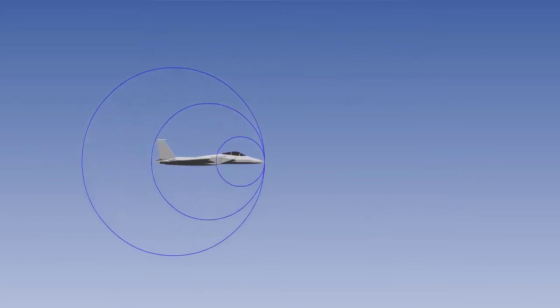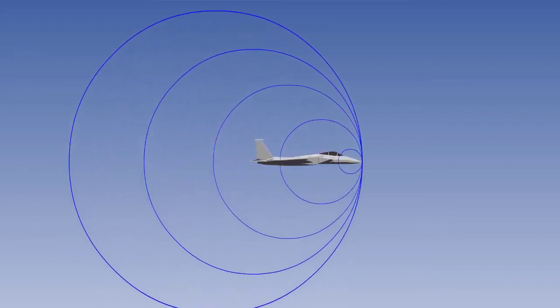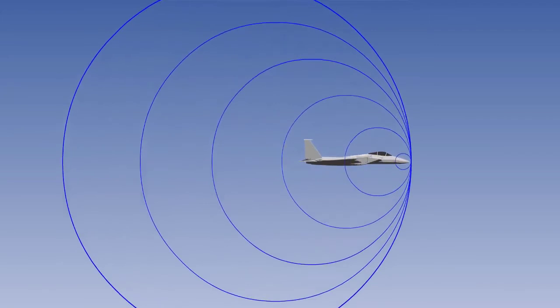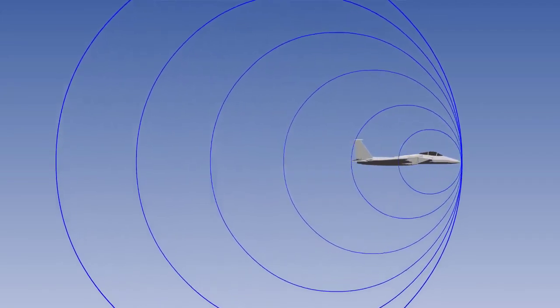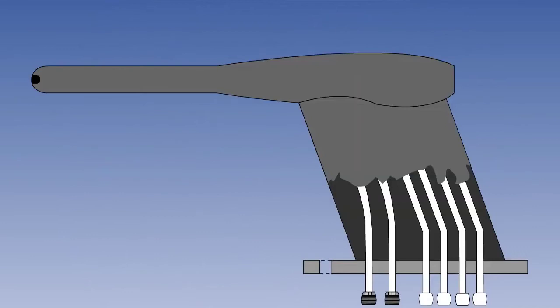For instance, aircraft designed for very high speed are unsuitable because the shock waves generated at high Mach numbers can produce significant errors in the pressure sensed by a static vent. On very high-speed aircraft, therefore, a more sophisticated combined pitot head or high-speed probe is used. This will have been specially designed to reduce position error, but will be more expensive than the basic combined probe found on low-speed aircraft.